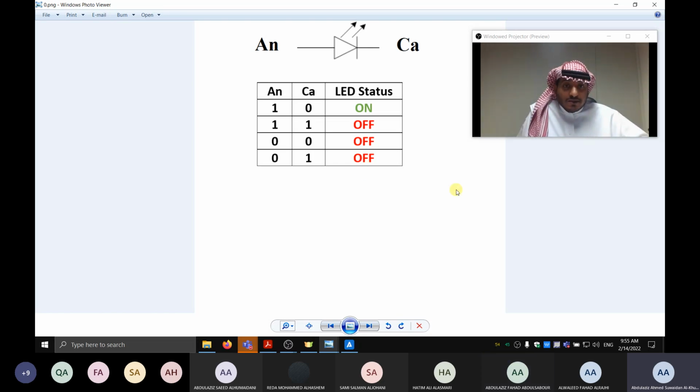Yes. So, also by experience, maybe some of you have experience with the LED light. If you want to use it in whatever project, you have to add some resistor to it. You studied that there is an internal resistor for the diode. I think all of you, when you study the diode, there is an internal resistance and then you do some calculation. But if you do projects and put an LED, you have to put some resistor.